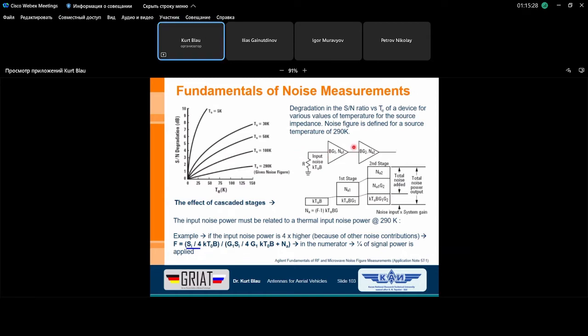If, for instance, the first amplifier has a smaller bandwidth than the second, then the overall bandwidth is determined by this first amplifier. Or if it's the opposite, meaning the bandwidth of the first amplifier is larger than the bandwidth of the second one, then the overall bandwidth is determined by the second one, no matter how large or small the bandwidth of the first amplifier is.